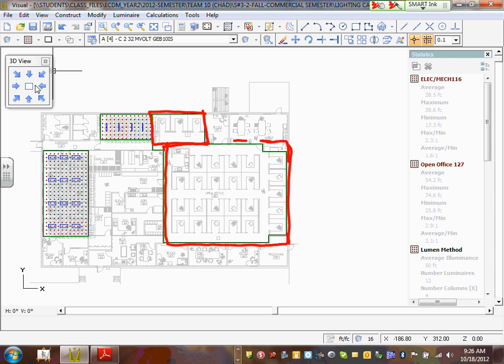I can't emphasize this enough, when you do the lumen method, do not drop the fixtures right on top of the model. Drop them to the side. Anybody know why we drop them to the side? Because we delete the background. We have to delete the background and only bring the fixtures. Can I have a thumbs up, Aaron, my friend? We delete the background and we bring the fixtures into our model.